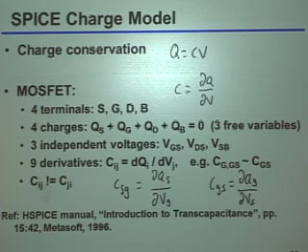Yes? I mean, not physically, like what's going on? Is there some fringe field effect that happens inside the device? So the question was, do you mean physically what's happening with that example that I just gave in terms of gate to drain versus drain to gate? Yeah, so what's physically happening there is that if you change the gate voltage, that will mirror some charge in the channel, right?